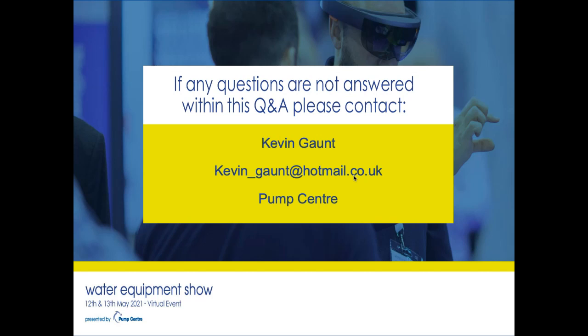The next question's from Amol, and they ask, what interval is required to re-grease the bearing, and how do they understand that re-greasing is actually required? The factors that determine how often you have to re-grease a bearing are the size of the bearing and the speed with which it's rotating, and that data is provided by the bearing manufacturers.